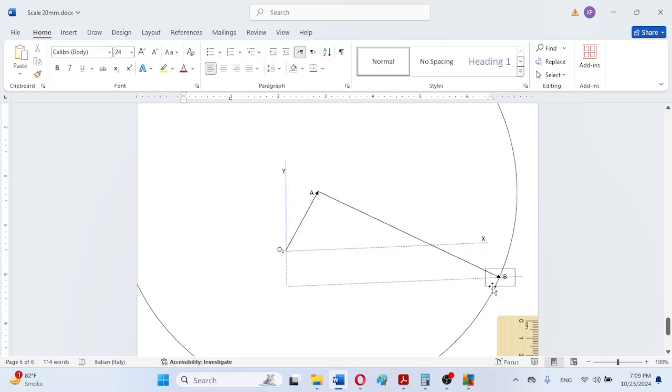So here is an important learning point: how we will be moving this complete diagram towards the right. We will be selecting this slider box, and then pressing the Control button on the keyboard, and as the plus sign appears, we hover our cursor and select these multiple objects, without selecting the labels, which will be moved separately.